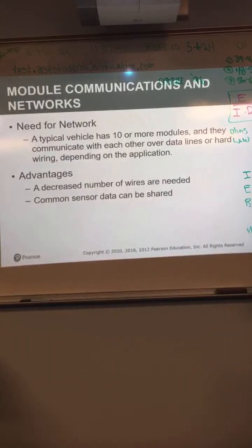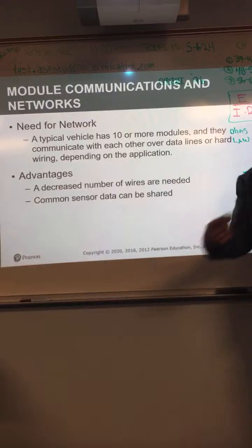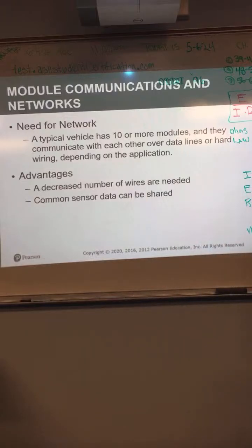So if I had like a 93 car and I took it to get registered or smog, I wouldn't have to worry about the check engine light? Well, yeah, that too. But if the check engine light's on one of those cars, it doesn't matter. They're tested through the tailpipe. If you have a car 95 or older and you take it to get a smog test, they don't plug it into the computer. They tailpipe test it. They actually check the HC, CO and all that kind of stuff through the tailpipe.